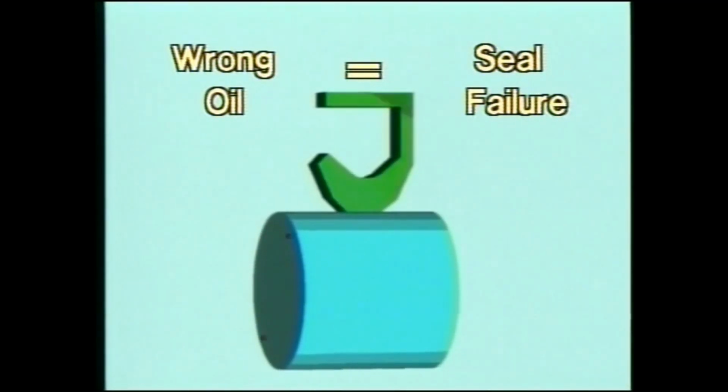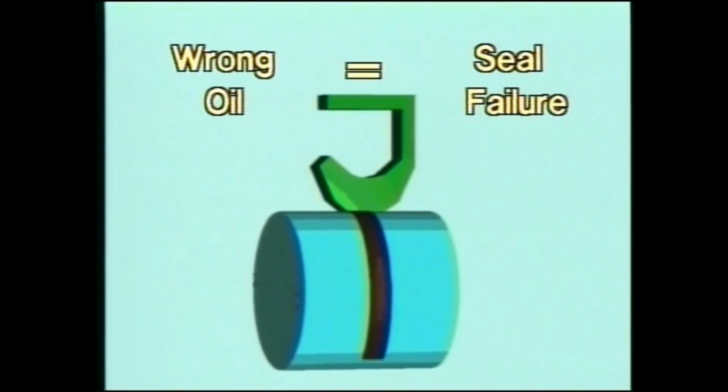Swollen seals wear quickly due to the increased friction from the extreme pressure on the rotating shaft. Leakage quickly follows. Pump bodies are also damaged from pressures that exceed manufacturer specifications. Technicians should never raise the pressure beyond the limits set by the manufacturer.